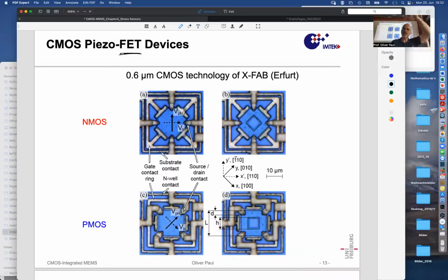Now there is a gate on top, so in cross section, you have the silicon component, you have your source and drain, you have here the gate oxide, and then let me draw the gate in yellow on top of everything. So here is S, source and drain.